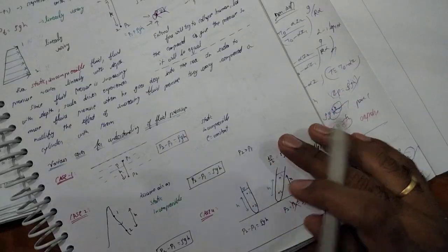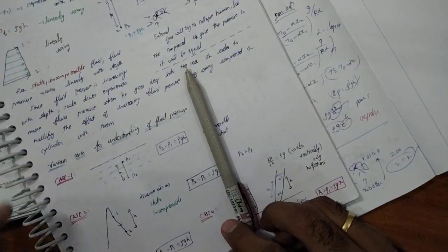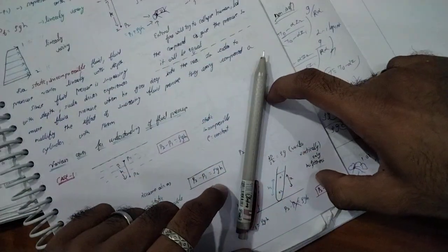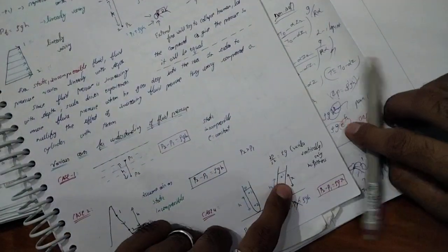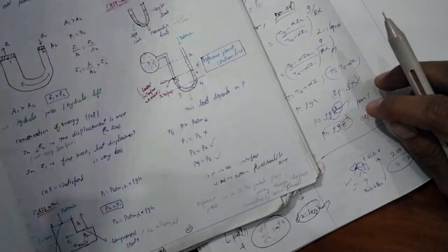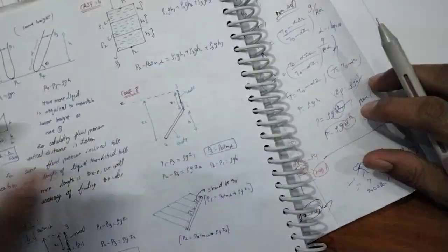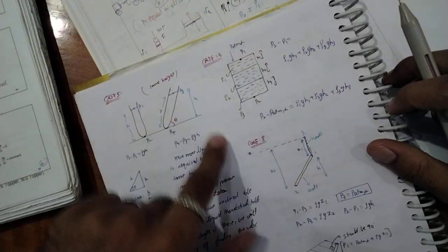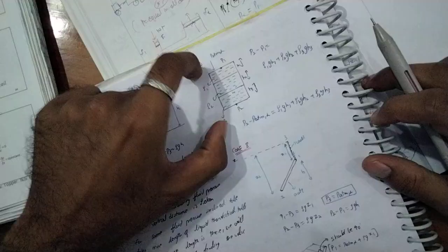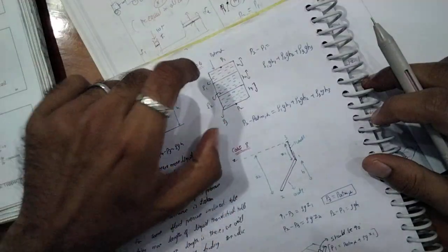So if this is a straight thing and you are taking the pressure, suppose you incline it also, you have to take this kind of height. Okay, this side only you have to take. You can see this height is P2 minus ρg of x. You should not take any other height. See, this height must be taken. So this is also another thing you need to look upon. Okay, I'll explain this when going to the problem.